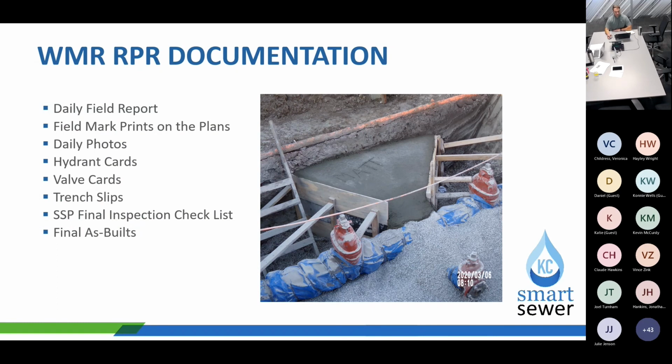So these are the type of documents that you really need. You need to do that daily labor force report every day. And then on the field mark prints, I always recommend on those field mark prints to do it in red or do it in blue. Do it in a different color than black. It represents, it's easier to find and know from new to existing, what's been installed and what hasn't.